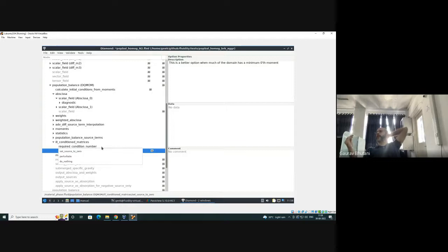So see, when you start, your A matrix depends on different abscissa values. Now when you start a system with a monodispersed system, all the particles have the same size, which is very realistic. Then what happens is your matrix becomes ill conditioned. So what we do is, we mathematically change the value of one abscissa slightly. So if one is equal to 2.0, the other becomes 2.001. So that perturbation results in getting out of ill conditioning. And then as time proceeds, the distribution will change because of aggregation and breakage, then it becomes fine.